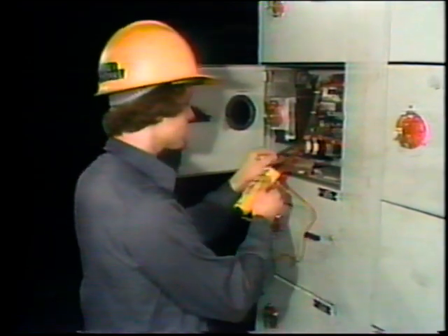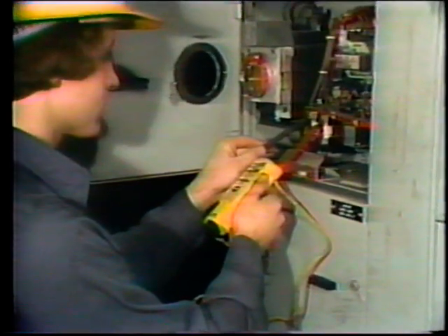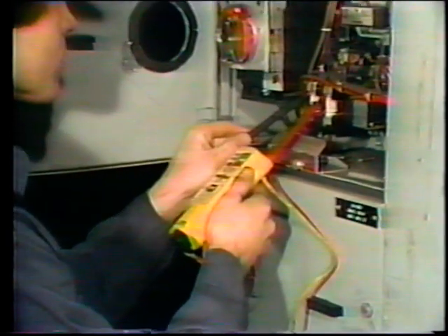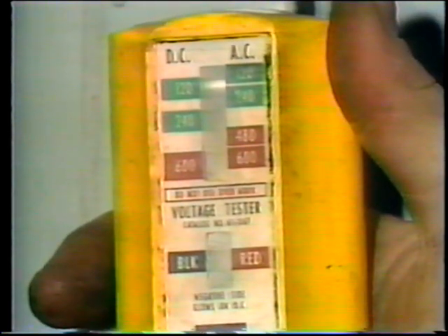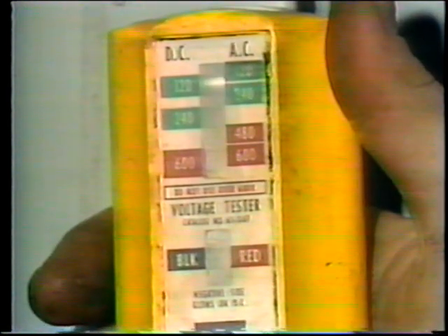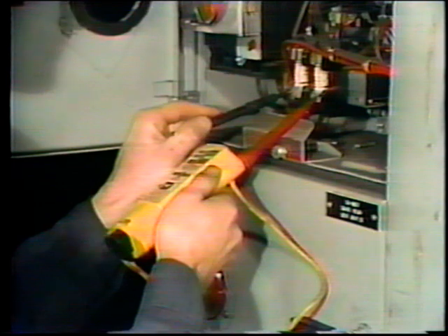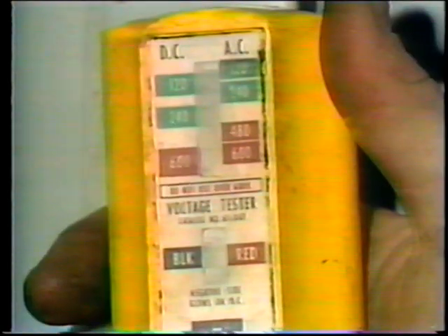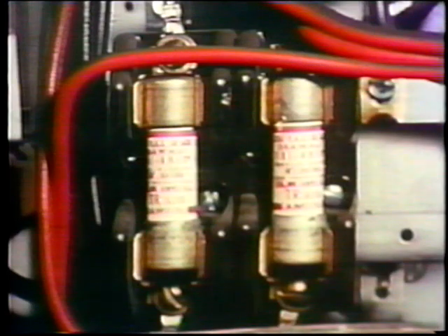The electrician checks voltage on the input side of both fuses to check if voltage is reaching the fuses. The reading indicates that voltage is present and that voltage is reaching the fuses. This means that the power supply to the controller isn't the problem. Then he checks output voltage of both fuses. There is no voltage present. This indicates that voltage is not reaching the output side of the fuses. One or both of the fuses must be bad.